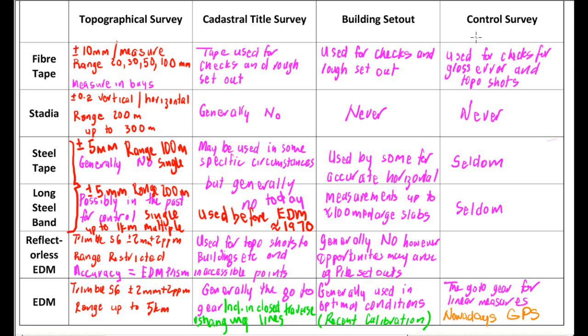These can be used for topographical surveying, remembering that with most EDMs there can be a coarse and a fine range. So the coarse range would tend to be used for topographical survey because the accuracy and rigour is not required. However, under certain circumstances, there's nothing to stop you using the fine or more accurate range or measuring methodology that's there and available.